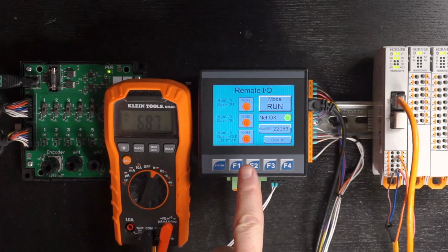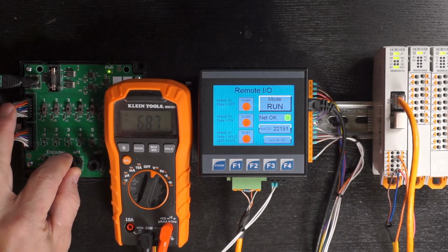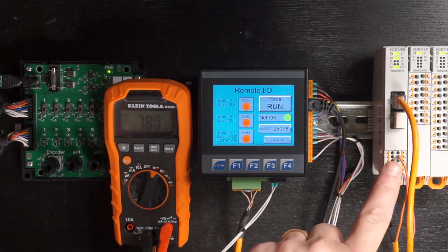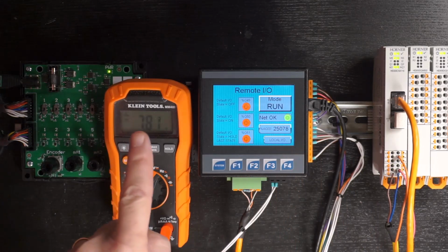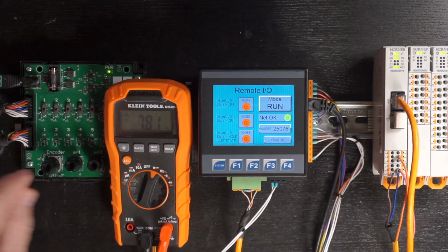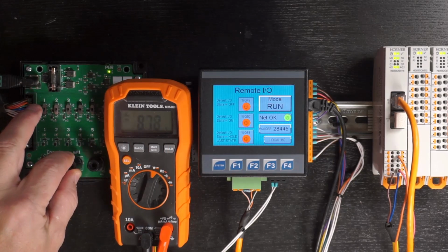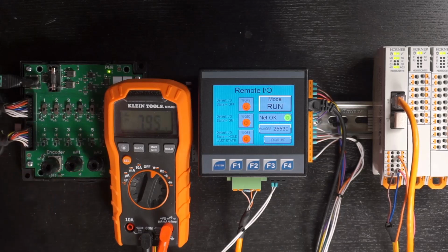So what's happening in logic is the OCS is passing the value from this first pot directly over to the analog output register that's controlling this analog output. You can see that digitized value there. All right, and this value on my multimeter is the voltage. It's a 0 to 10 volt output. You can see my voltage going up. And then as I turn around the other direction, you can see the voltage going down. All right, so let's stop here at about 7.95 volts.